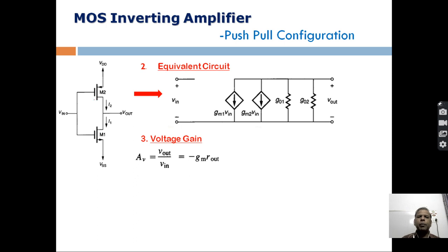But in the present amplifier circuit the situation is a little bit different. Here we have two amplifying devices, right? So we have two Gm components because both amplifying devices are contributing Gm to the gain of the amplifier. Which Gm are we going to use here? It's very simple. Since both components are contributing, we have to include both of them.